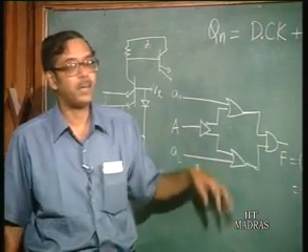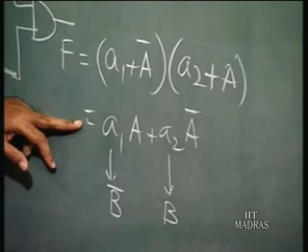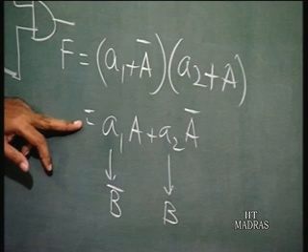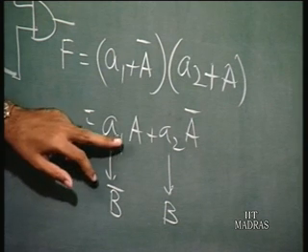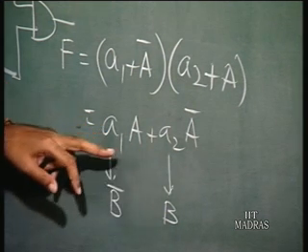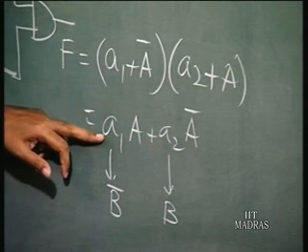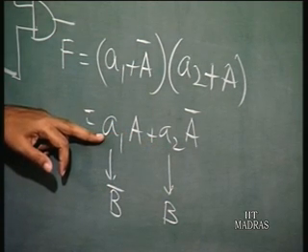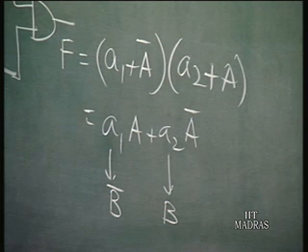Now, when you compare this with the standard function which is realized in a D flip flop, you see it is quite similar. So, what you have to do is, the clock input must come as the control input here, or A should become the clock, and in one case A1, the small a1, it can be D, and the other one should be Qn minus 1. All right. So, if you do that, you will realize a D flip flop.